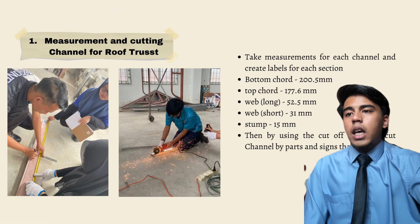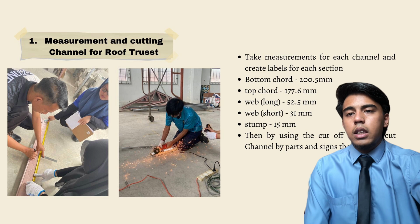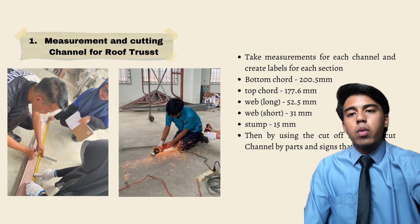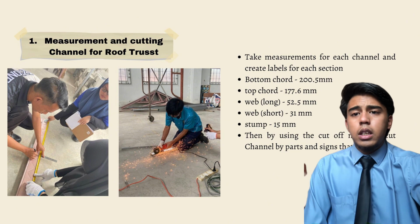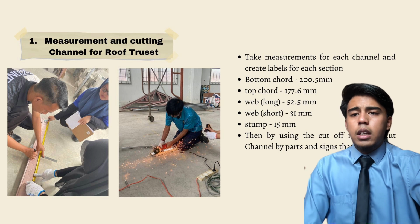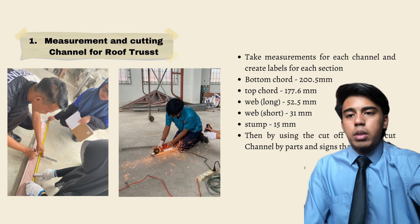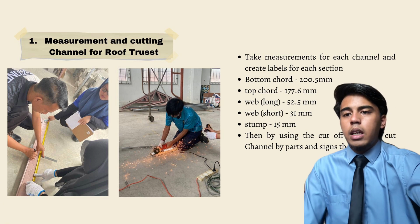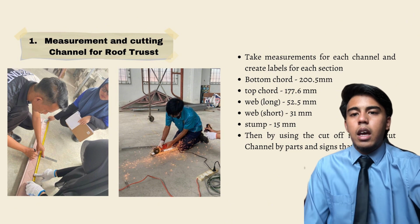First, measurement and cutting channel for the roof truss. Take measurements for each channel and create a label for each section, for example, bottom chord, top chord, long web, and short web. Our length of the bottom chord is 205 mm. For the top chord, 177.6 mm. Long web 52.5 mm, short web 31 mm, and stump 15 mm. Then, using the cut-off machine, cut the channel by part and sign that have been set.